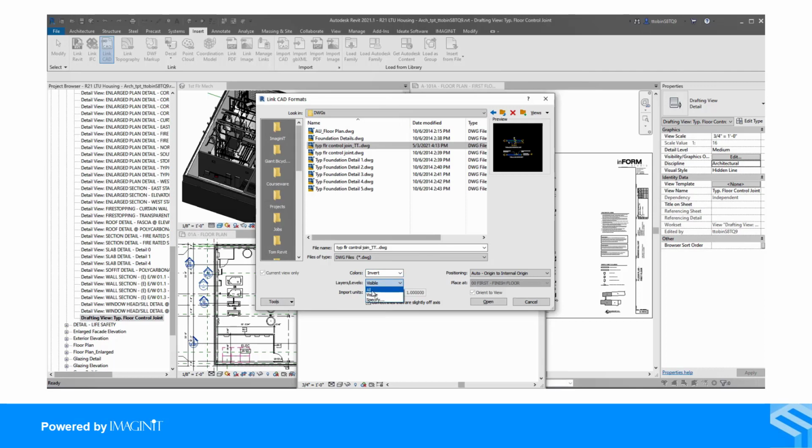Okay, then you can bring in layers and levels. It includes levels because that's what layers are called in MicroStation. You can bring them all in. You can bring in what's visible, or you can specify. If you specify, you'll get a dialog once you hit the open button, and then you can pick the levels or layers that you want to bring in. I like to bring in what's visible. This is also why I like to do a little work ahead of time and just get rid of everything else in case I don't pick this option. I bring them all in. I'm not bringing in a whole bunch of empty ones that I don't need.